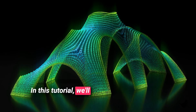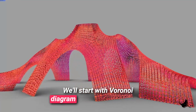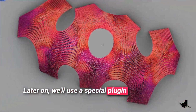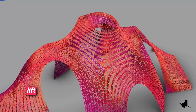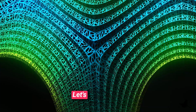In this tutorial, we'll use a couple of different plugins to create this panelized tensile structure. We'll start with Voronoi diagram to get the curves, then expand the mesh and let Kangaroo do its magic. Later on, we'll use a special plugin called Striper to get mesh strips along defined direction, lift internal points, and lastly, map our tiles and give it some coloring with gradient components. Let's get started.